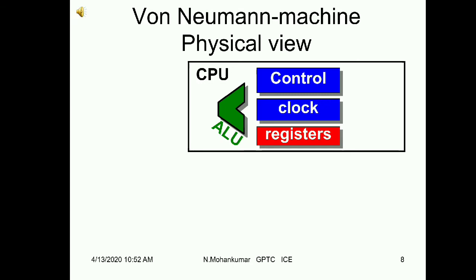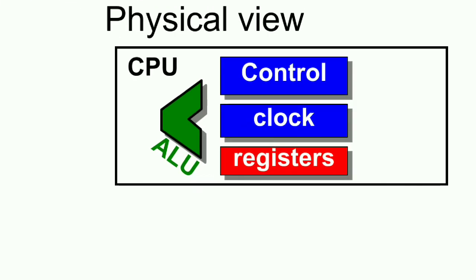And registers. Registers are another small circuitry. Here, register refers to a group of registers. A register is nothing but a group of flip-flops, maybe D flip-flops. Let us consider an 8-bit register formed using 8 D latches or 8 D flip-flops connected together. It can store 8 bits of data temporarily, if it is an 8-bit register.